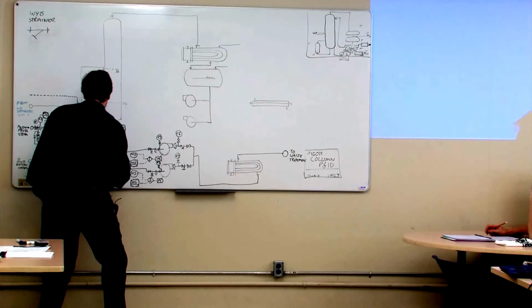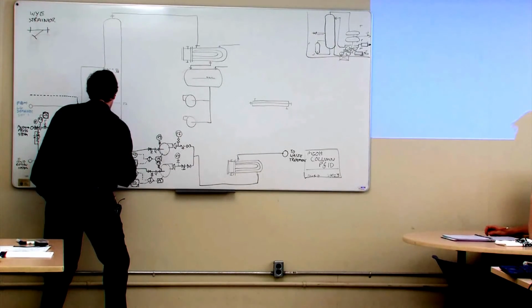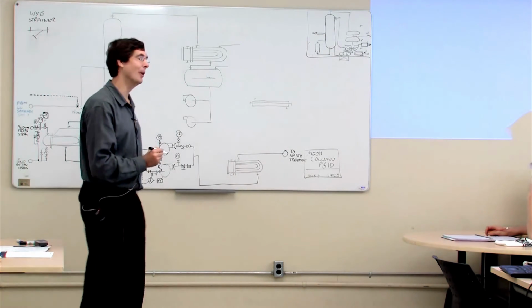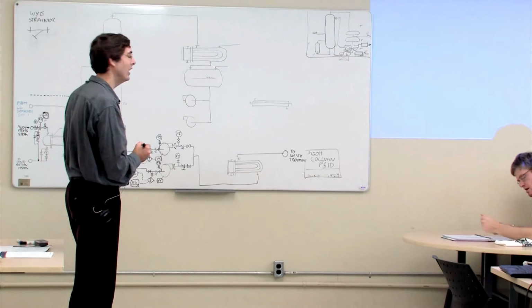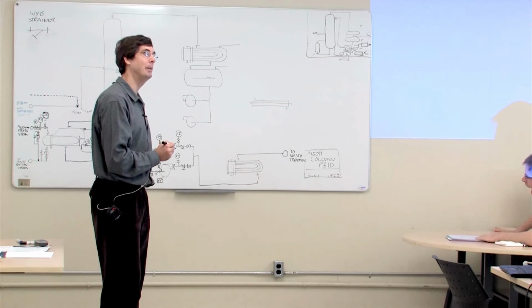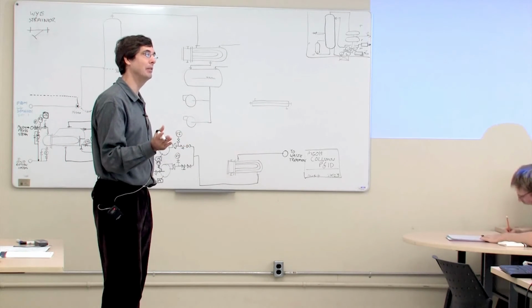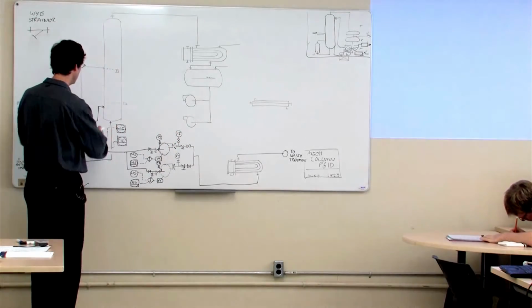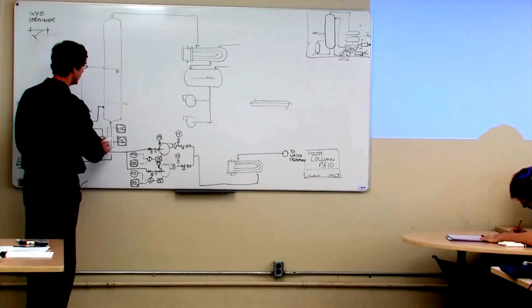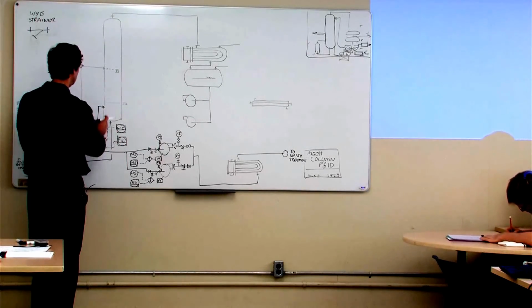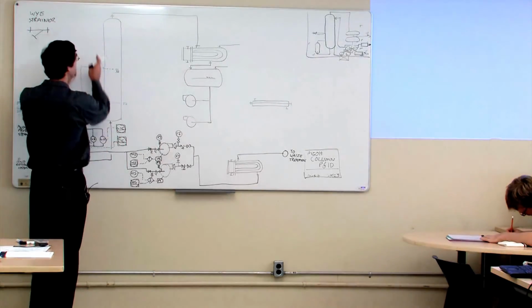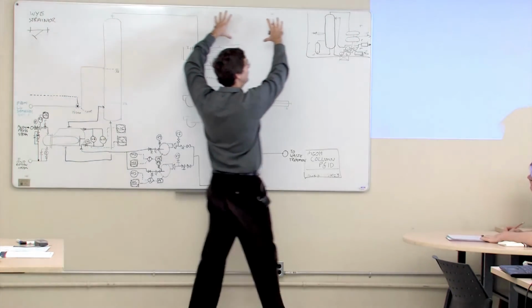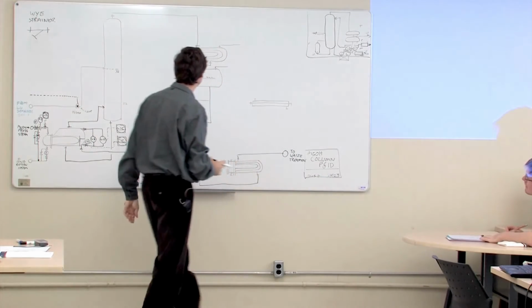There's an old style of P&IDs. There were two competing styles a long time ago. It's an interesting story. I think DuPont had one style, and I forget what the other company was. DuPont's style was to draw the field instrumentation like this, and then draw all the control wires up to the top of the P&ID, and then all the indicators and controllers would be on the top of the P&IDs like that.